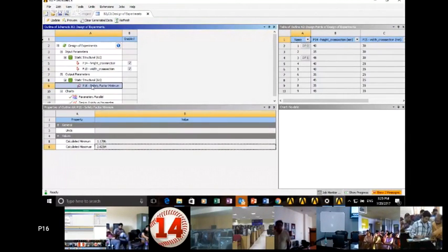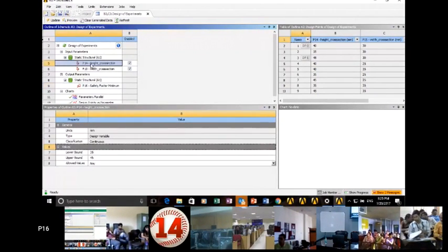Previously in the what-if study, we were randomly assigning parameters. We had no idea how many iterations it would take or from which value to which value. Over here, we can overcome that limitation by giving a range of values. For example, when I click the first input parameter, it will ask me for the lower bound and upper bound.